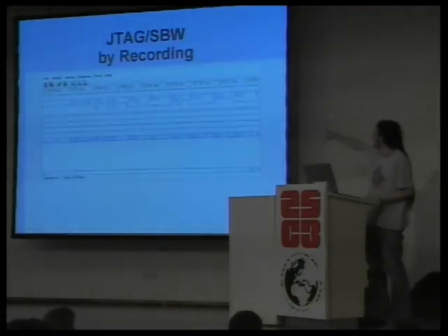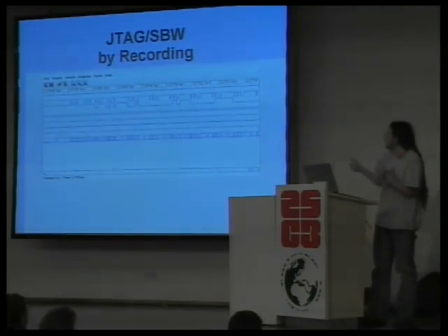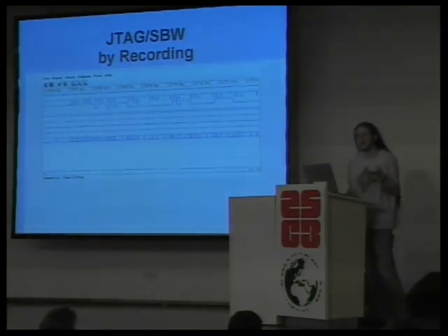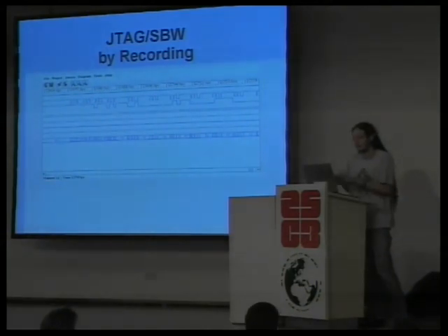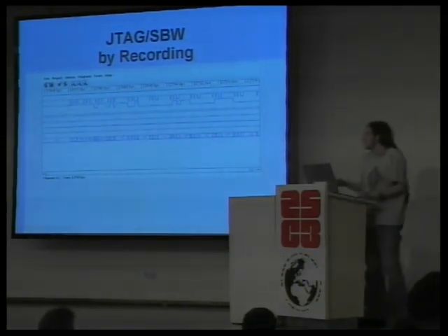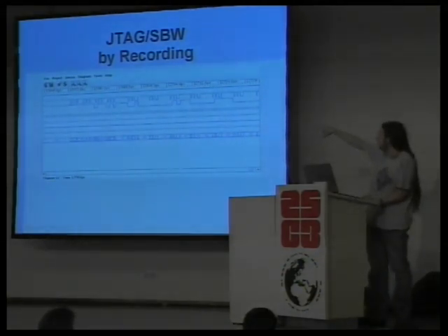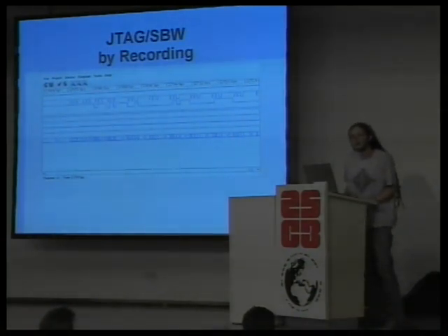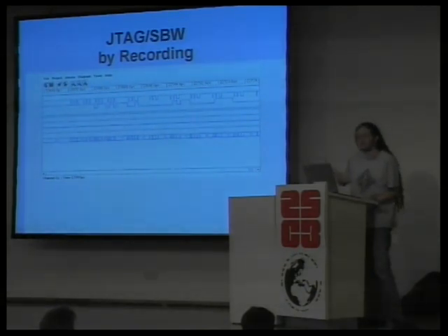Yes. So this recording is from an FPGA that has been reflashed with a bitstream to make it behave as a logic analyzer. And then the software that you see connects to it through a serial port. When you push a button, it does a quick recording at up to 100 megahertz. And then the recording gives you the logical value of each pin at each moment in time. This is also available in a text file that can be parsed by script.